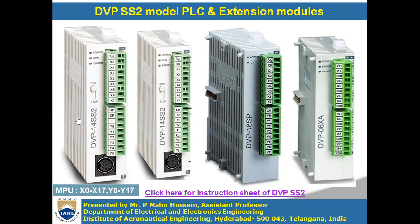Okay, so this is one model of DVP series 14SS2, right? So this is a transistor logic PLC, right? Which means that inside this PLC, the contacts are made up of transistors. The transistors may be PNP type or NPN type. Okay, so now if you observe the second one is also the same DVP 14SS2 model. But this PLC is a relay type model. Okay, the first one is the transistor logic model, and the second one is the relay type model.